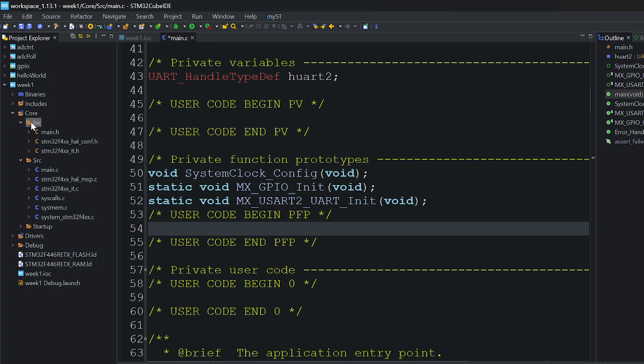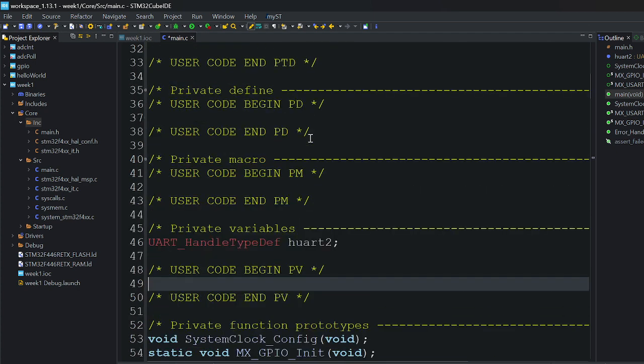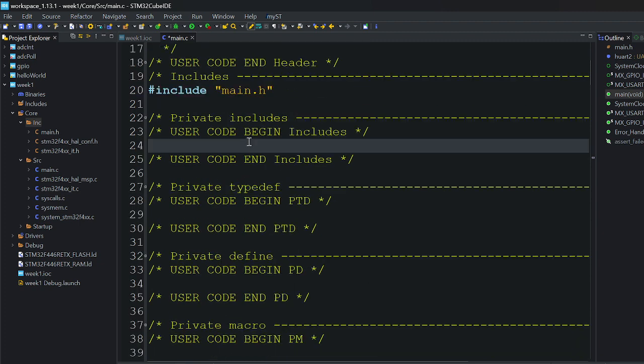That's awesome. But then I need to reference it. So in main, you go and say, where are my includes? If I have a thermistor.c and a thermistor.h, you include thermistor.h right there. Yeah, H is the prototype and C is the actual code, the definition, that is going to be coming in. Yes. Okay. And so we're going to do that. I'm going to show you when we start doing the next lab.